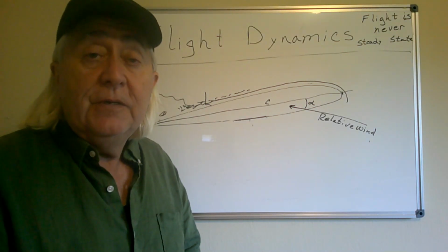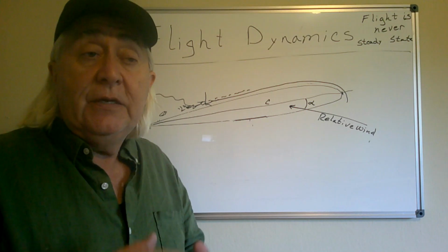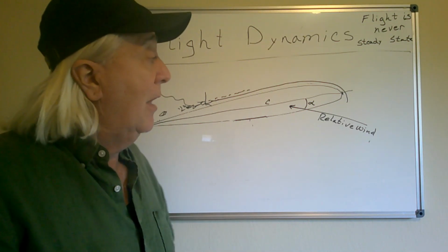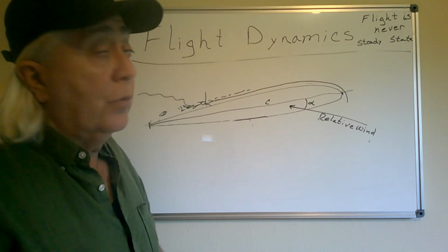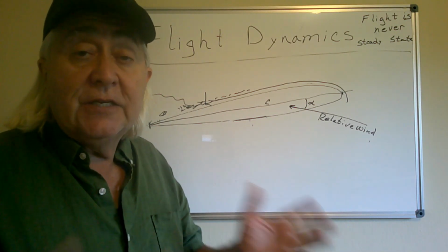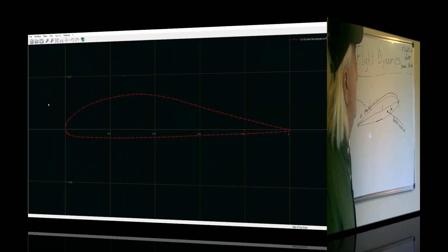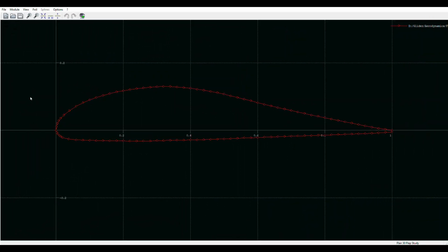So remember, angle of attack has to do with the relative wind and not with the configuration of the aircraft relative to the ground. And we're going to hunt around for a solution that shows a drastic loss of lift almost instantaneously. Hey, welcome to the wonderful world of computational fluid dynamics. I am here in my den running Xfoil, version 6.61.